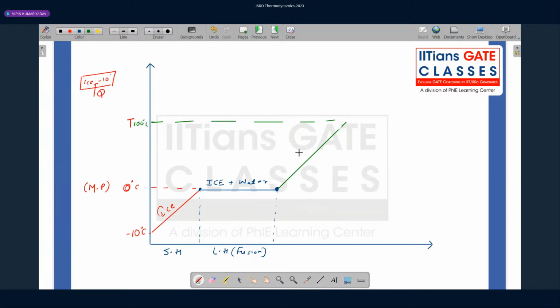We have reached 100 degree Celsius. So this is simple water. Only temperature change is happening. Temperature of water is increasing from 0 degree Celsius from here to 100 degree Celsius here. Now what is this 100 degree? It is the steam point. It is the saturation temperature. Now the phase change will happen. So whatever heat is absorbed till here, it is called sensible heat. After this, the phase change will start, that is, water will start converting to steam.